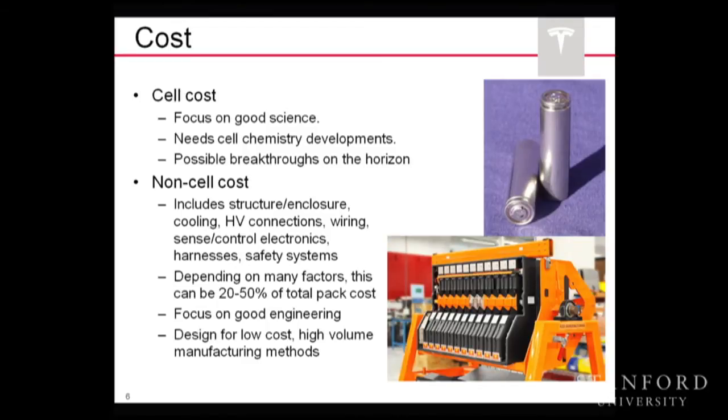Some of the packs are very low density and they blow air through them to keep the temperature down. We use liquid cooling, circulating a coolant, basically like the fluid in your radiator, through the pack to maintain their temperature. There are cases where we actually heat them up because they have a preferred temperature operating range.